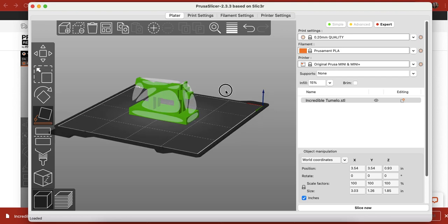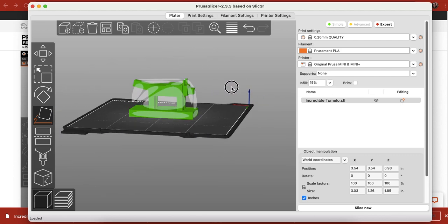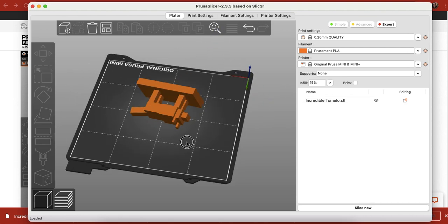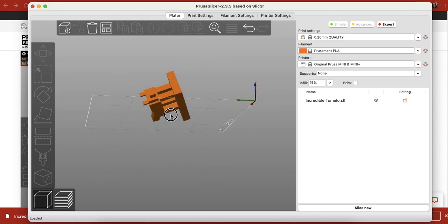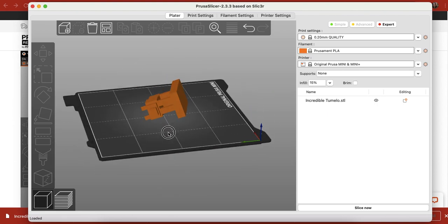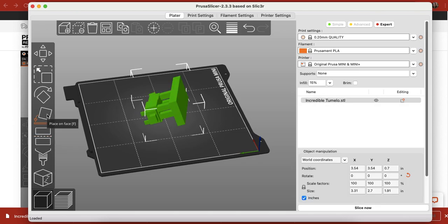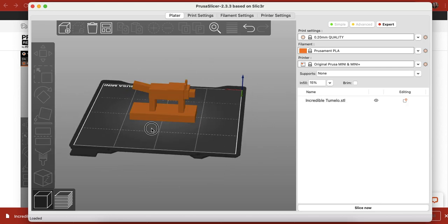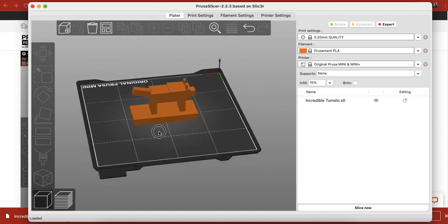This is important to note because oftentimes when we bring an object into the work plane, we want to place it on the face that's going to have the best results when printing. So for instance, if I place it here, that might not be as successful of a print. 3D printers often print layer by layer, and so going up, there isn't a lot of room or touch points with this printer. So printing in this direction might actually fail. We want to give the printer the best chance for success, so we want to put it on the best face. In this case, that would be this one right here. It's a flat surface. It's allowing a lot of flexibility when it comes to providing the support and stability we need for a 3D printer.